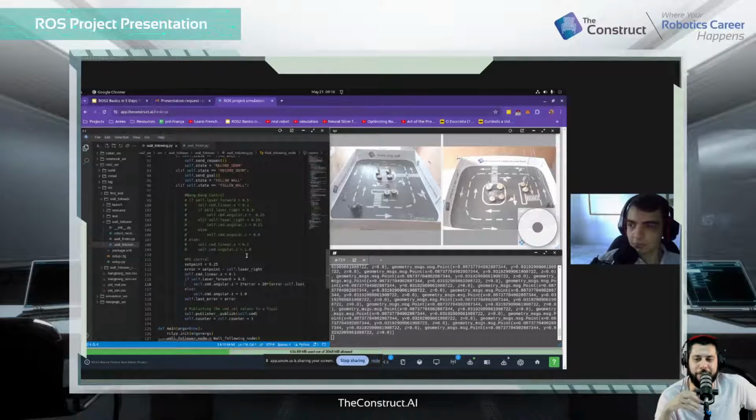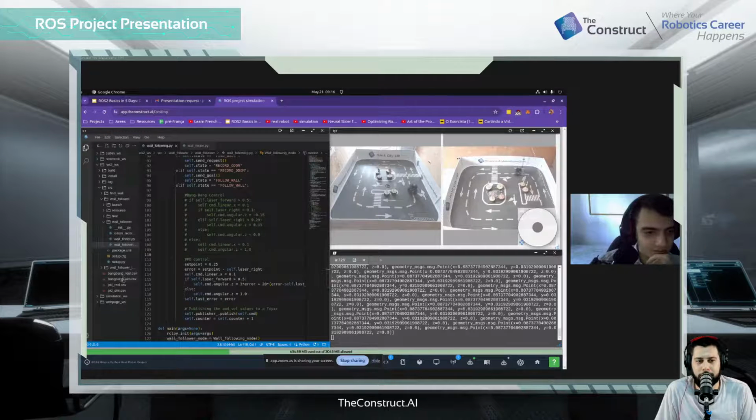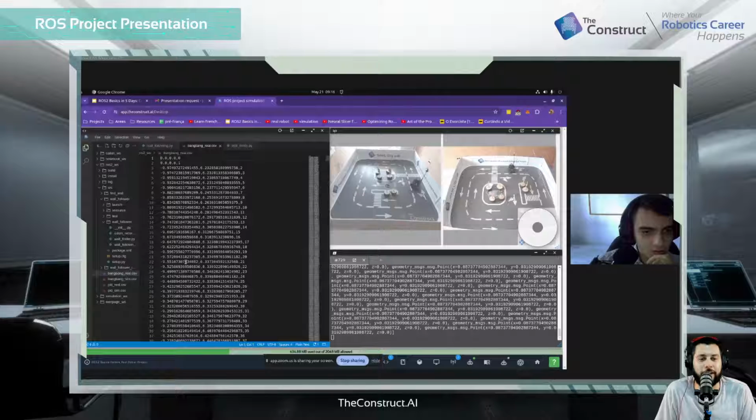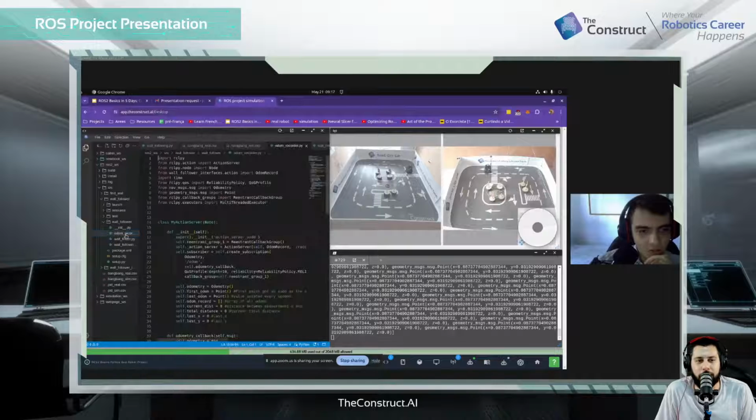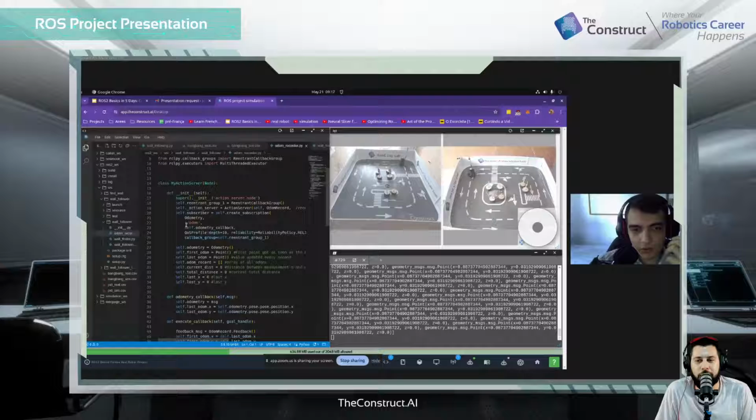Can I ask, how did you do that? So I thought about using a ROS bag, but it was easier to just use the CSV. In Python, import CSV, and I have the CSVs here. I just did a bunch of CSVs of the odometry in simulation, which was more straightforward than the ROS bag. Of course, if I wanted to gather information to use in a later simulation, I would need to use a ROS bag.